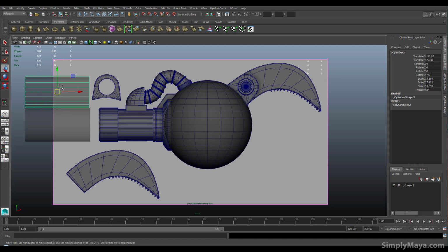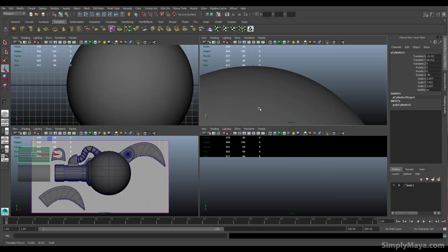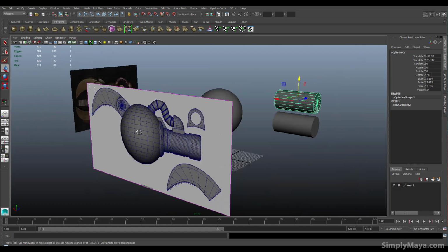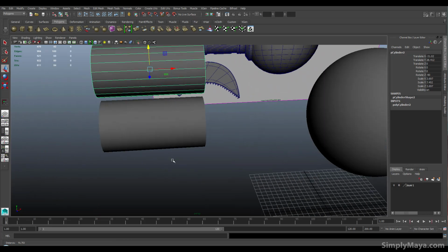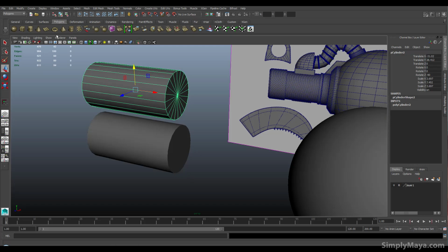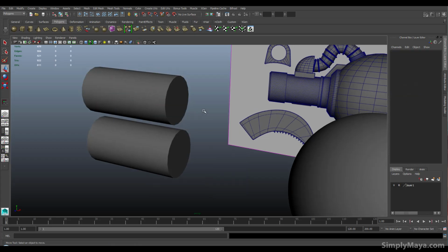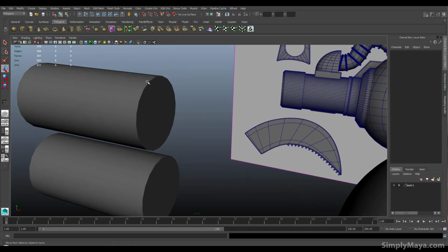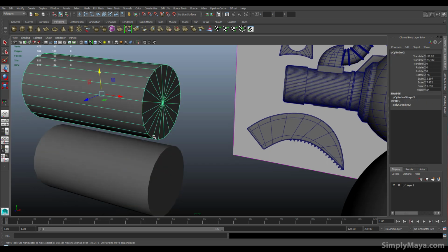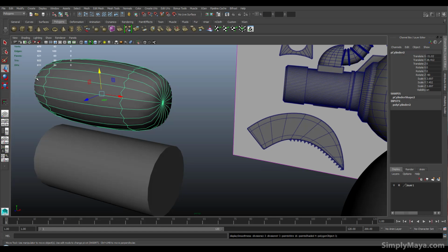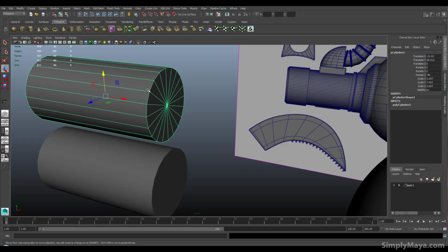Okay, now let's see what happens when one of these is smoothed and one is not. So I'm going to disappear into the viewport here. Okay. So, I'm just going to check my viewport 2 settings to make sure I have anti-aliasing turned on. I do not. So let's turn that on. That'll help us get a better look, and also I'll flick on the ambient occlusion. Alright, so as you can see, this is fairly jagged, as is this, because these are identical objects. So if I hit 3 on the keyboard to smooth this, it'll completely collapse in on itself. So the first thing we'd need to do is add some edge loops around here and here, just to make sure that that doesn't happen.